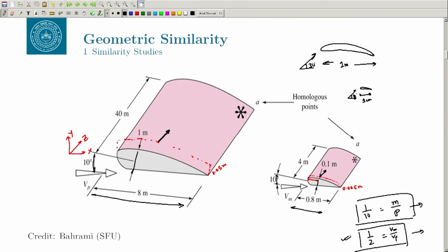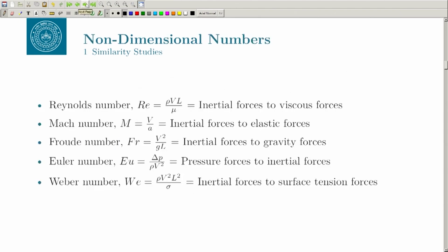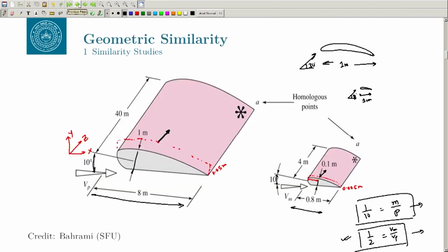Now, that is about kinematic similarity. The last one is the dynamic similarity. Let us take the example of two aerofoils, which I have drawn here, and talk about the forces here and here. The dynamic similarity says that at corresponding points, the forces on the body should be in the same direction and must be scaled by the same factor.